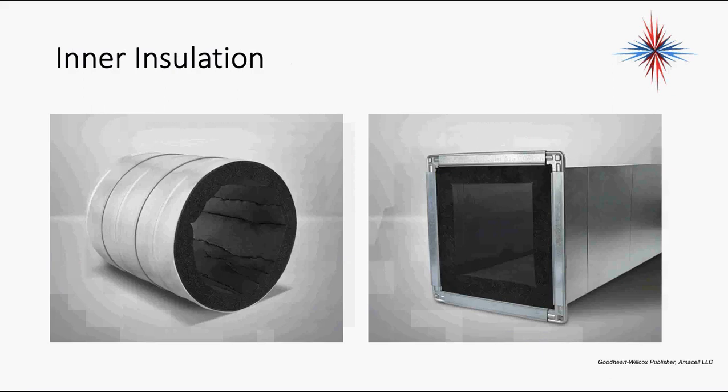We have two ways to insulate ductwork. Both of them have different insulation values and purposes. Insulating ductwork on the inside is by far the most efficient from an energy standpoint. It also breaks sound.